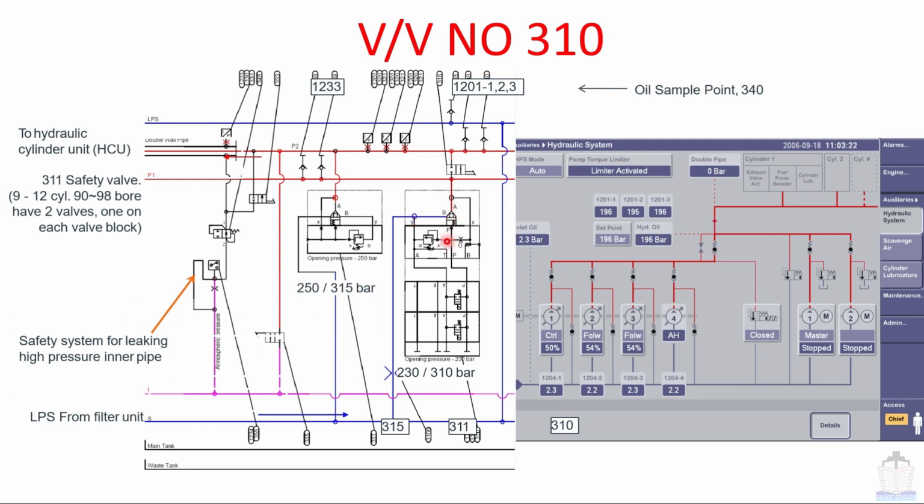And this depressurization of the oil is done by three methods. The first method is by hydraulic oil itself, which activates this pilot valve and hence this main valve opens. Another method is by these two solenoid valves. These two solenoid valves work in parallel. This solenoid valve also depressurizes this part. How? You can see a line is coming over here. When it is activated, then this line goes directly here and drains out. By doing so, this area's pressure goes down and hence the main valve opens.